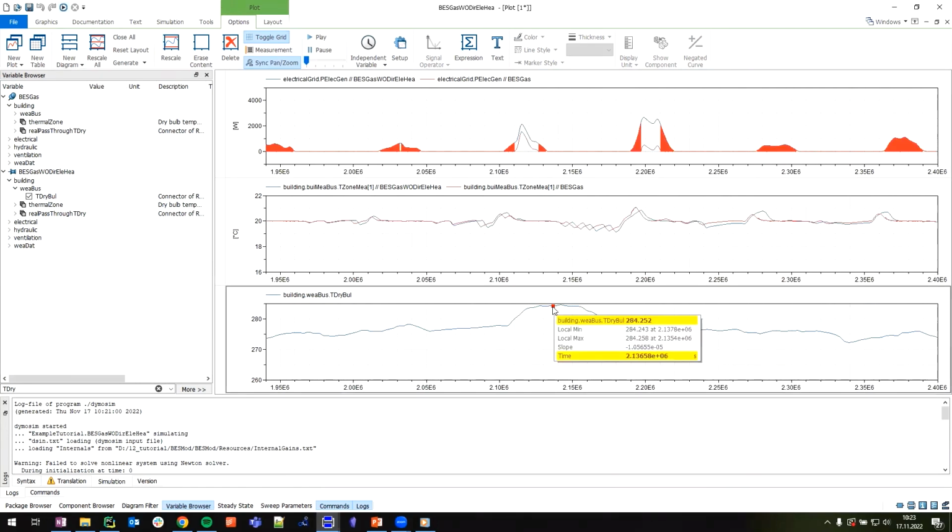And that could be due to the elevation of the heating curve used to control the boiler not being set properly for the building model. So you could optimize this a little bit, but still the deviation to 20 degrees Celsius is not that big. So in here we only see a slight improvement. But what we could, for example, do in a study is, we are not actually shifting any energy. So we are only controlling the direct electric heating to achieve the room temperature the boiler wants to achieve anyway.